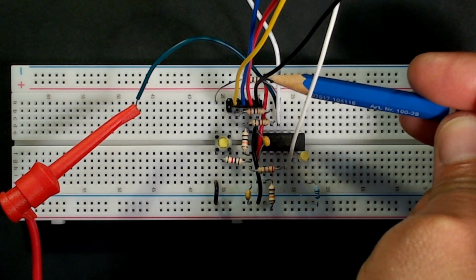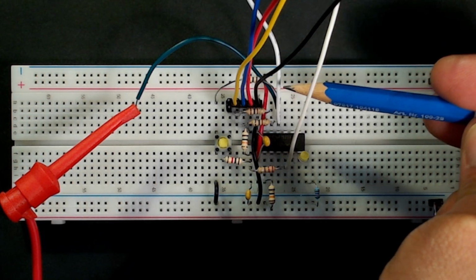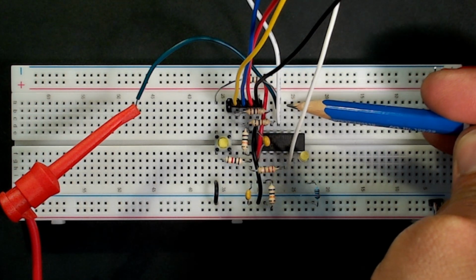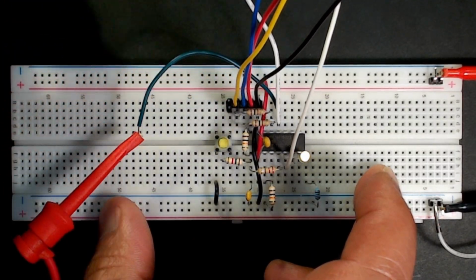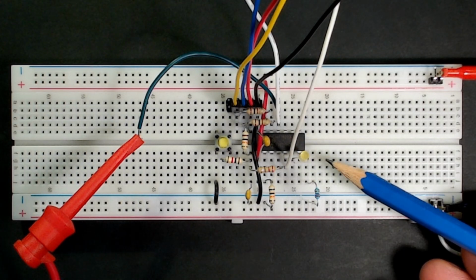Okay, I've officially lost my mind. It should have been working at that stage, so I've been trying to figure out what the problem was. Yeah, I figured it out. There's a resistor back here that's really tough to see, but it was put in place to ground the pin RA0 when we weren't using it. But we're kind of using it now. And of course, I forgot to remove it. Oversights. Now we have a beautiful blinking LED.